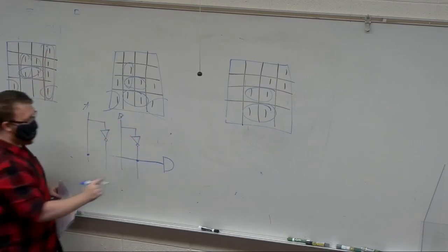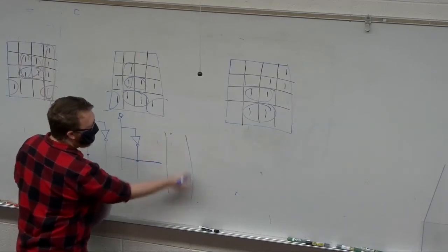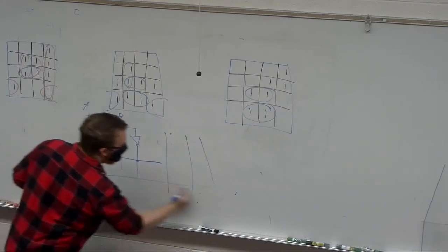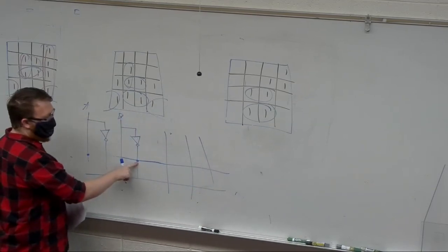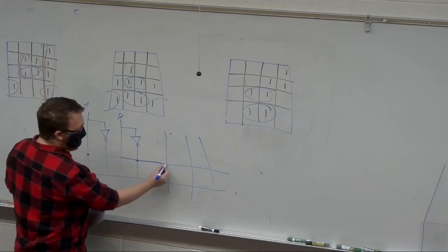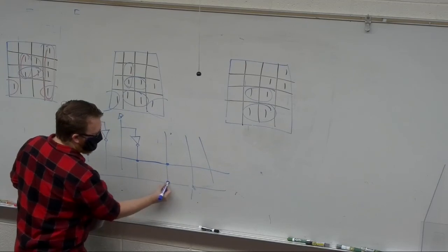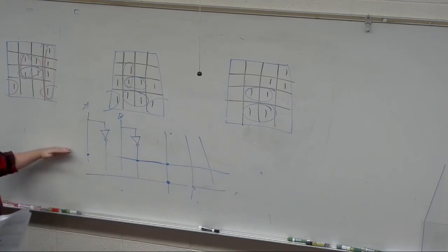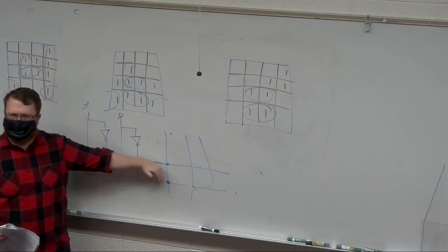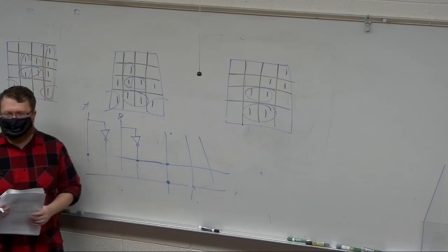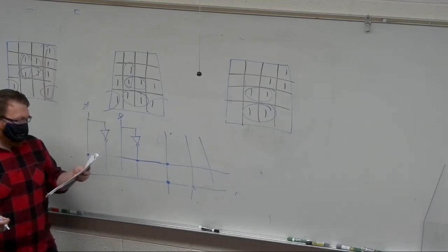But they'll take it a step further, and they won't even draw the AND gate. They'll just draw vertical lines here. So now we're implying A and not B, and then you have this or that. Oh, sorry, this or that, right? So if you share a horizontal line, you're ANDed, and if you share a vertical line, you're ORed. That makes sense in that notation. It's a weird but useful notation.